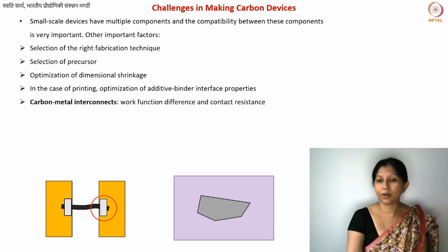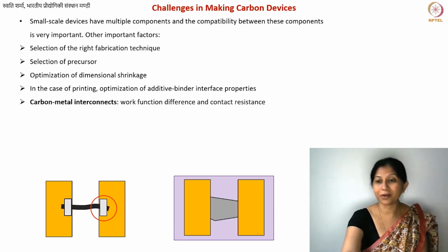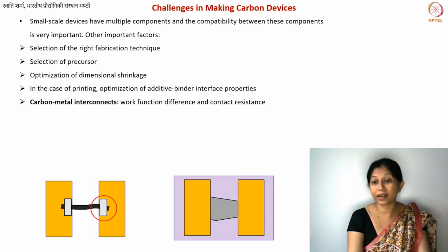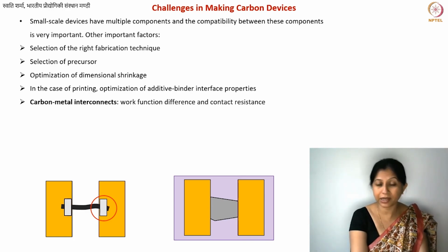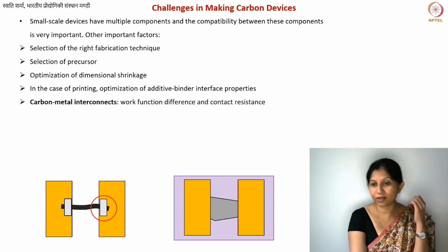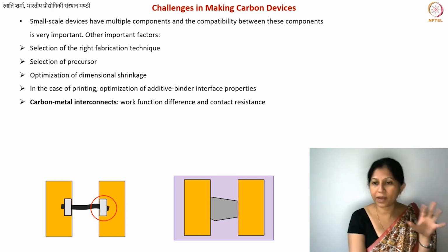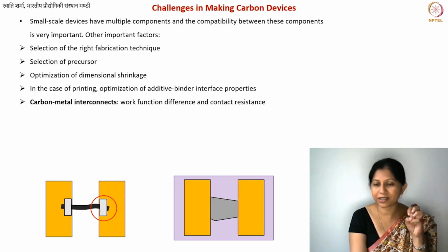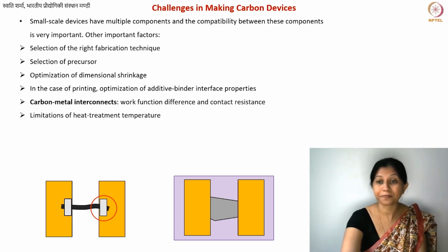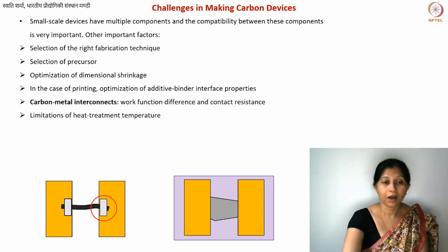Let's say you have a graphene flake on top of silicon oxide, and now from on top of that you can sputter your metal contact pads. But in this case you will see I have made much larger contact pads compared to what we had in the case of carbon nanotubes. So you may have to play with these fabrication parameters a little in order to get your optimum performance from your device, and reproducible.